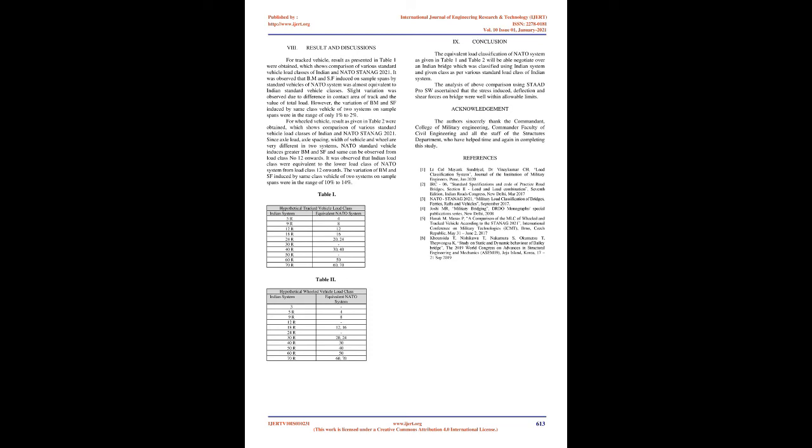Further, the BM and SF as obtained for the NATO system were plotted on the classification curve of the Indian system and results were ascertained. One such set of charts, BM and SF, is presented as Chart 1 and Chart 2, which represent the BM classification curve and shear force classification curve of tracked vehicles respectively. The comparison table obtained above was further ascertained by modeling the above span bridges in STAAD.Pro software and applying the above vehicle loads on the bridge model.